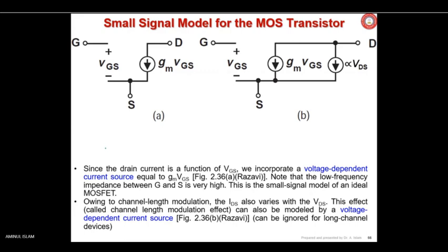With this property, we can say that it is a voltage controlled current source. If I draw ID versus VDS, for a particular VGS the current will be constant in the saturation region. If I consider this, then we can represent it as a current source. What is the current source? Definition of a current source? Can anybody say? A current source is what? An ideal current source, for example. Example of a current source, and what is its characteristic? Can anybody say?